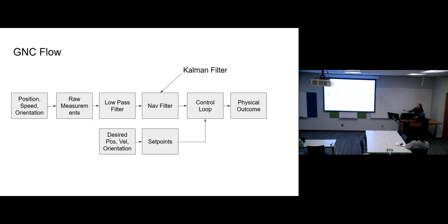It doesn't have to be a low pass filter. It could be a band pass. It could be a high pass. I mean, it depends on what your application is. It almost never, as a rule of thumb, hurts to have a low pass filter somewhere in your control loop. Unless you make it really coarse, I've never seen anyone where it's not almost always a good thing. So that's why I put that there.